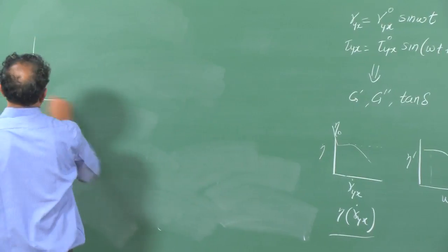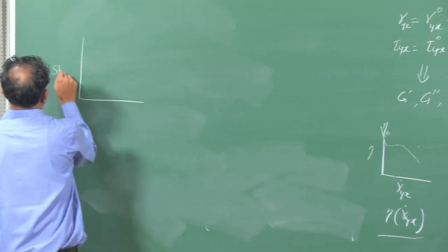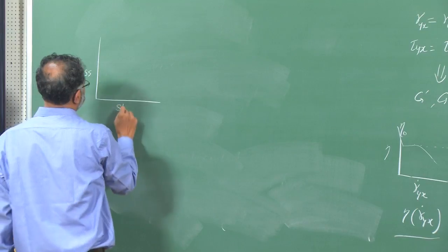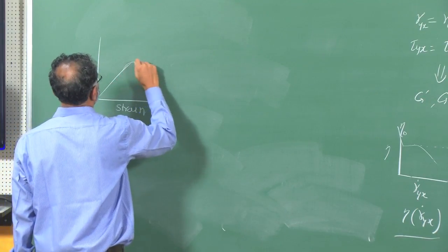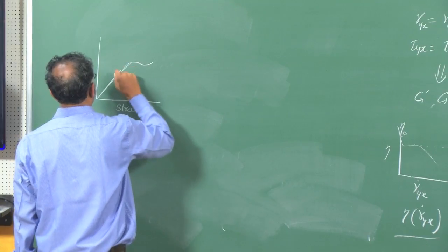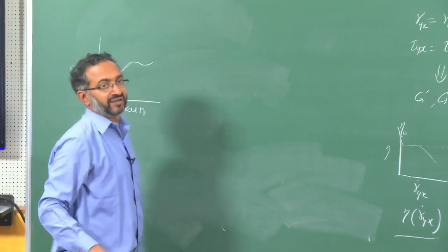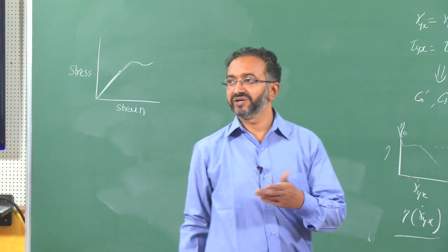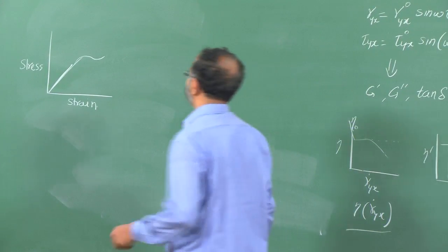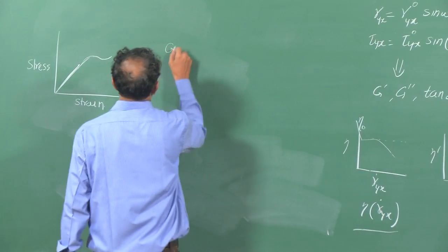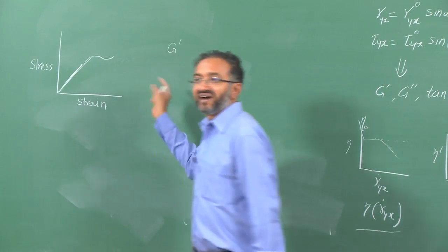So, you measure stress and strain and then you get a modulus, right. The response may be complicated, but in the initial elastic portion you get what is called the Young's modulus of the material, and then we are now measuring this G prime. So, are these two related?